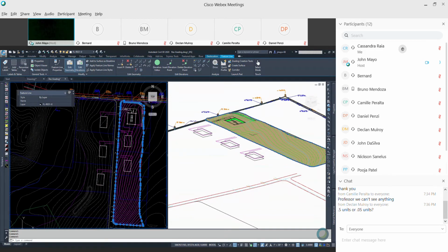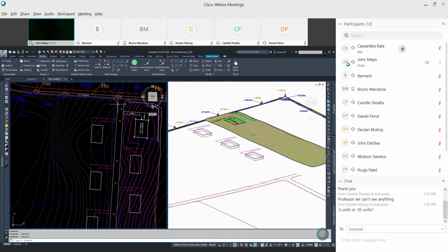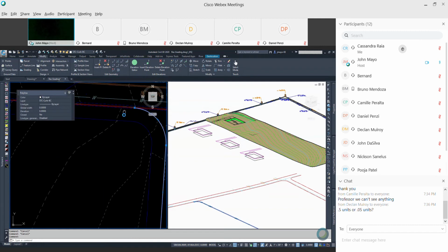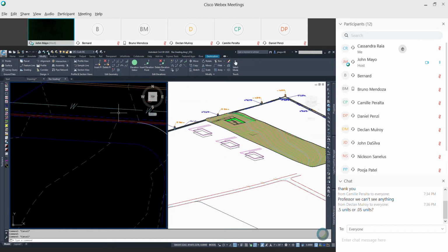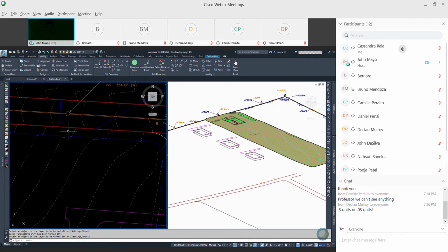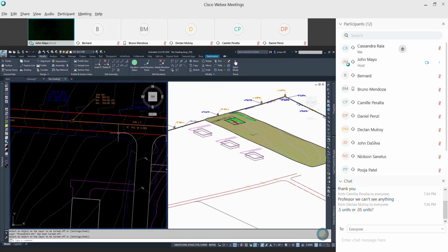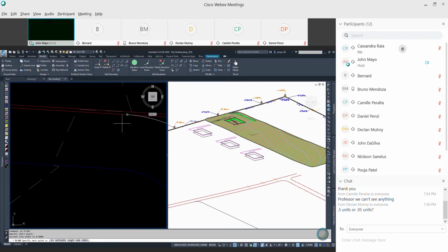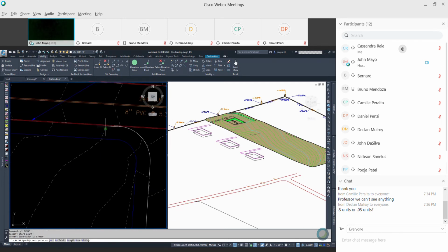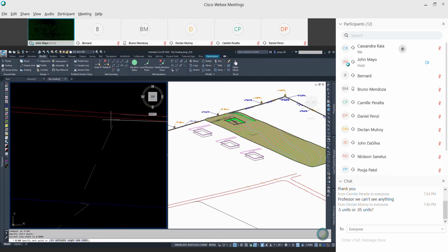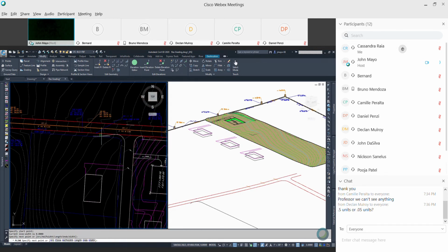And I'm going to do the same thing over here. I start with my top of curb polyline. And I use logic, basically, to determine where he's going to grade to. And I know when someone buys this lot, they're going to regrade right to this here. They're going to keep this, but they're going to hold the same. So I'm going to draw the polyline from here. And I'm just going to come to the top of the curb, or somewhere close to it.